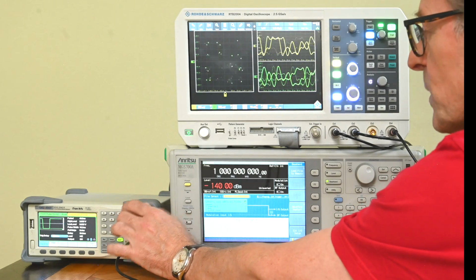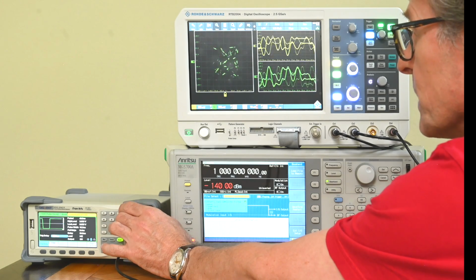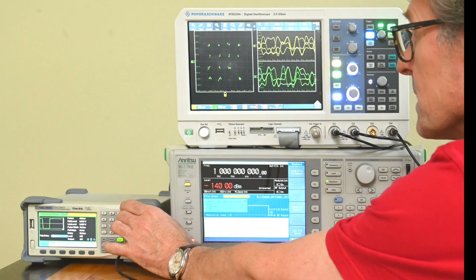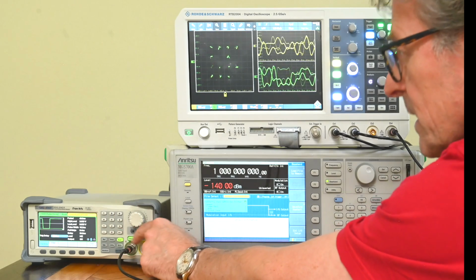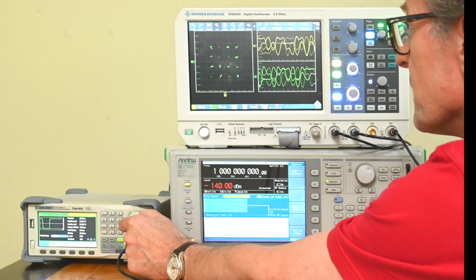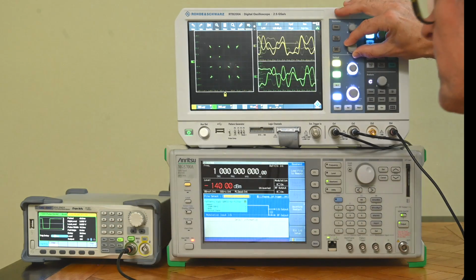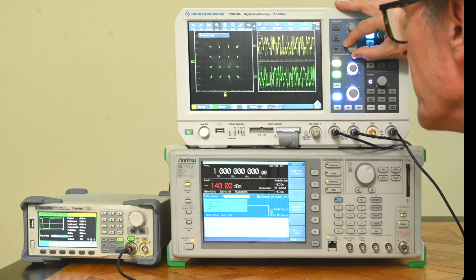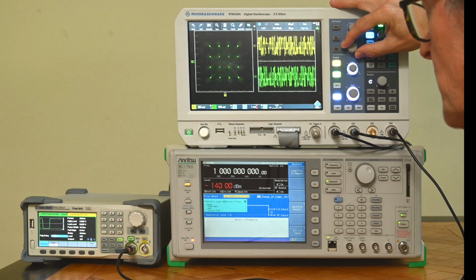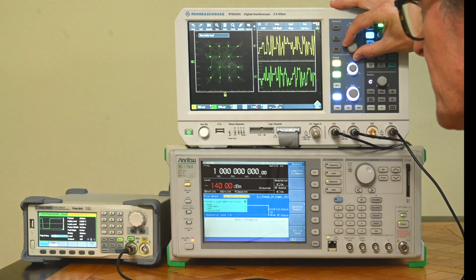I already see what seems to be a constellation diagram, but it's not perfect yet on the spot. So let me play around a little bit with the delay here. Now we seem to be getting a little bit closer. Let me go into the fine setting. Now this already looks more like a constellation diagram. Let me put it like this. I moved the button around a little bit more, and now I think we got more or less the diagram that we're looking for.